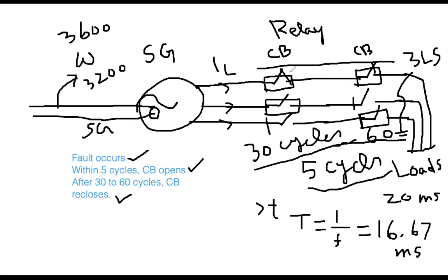Now everybody look, the breaker reclosed after this time, that is fine. But still the tree has fallen and the tree is a good conductor, still causing high current. So even though you reclose the breaker, high current will again flow through this one. So then the controller of the circuit breaker will understand that something is still wrong, something is going on.